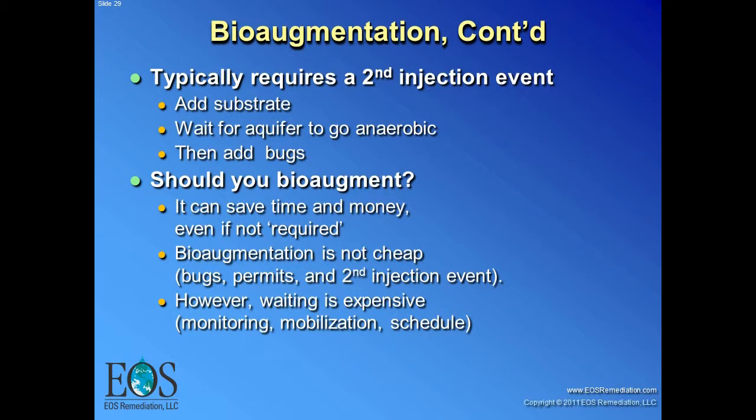The question is, should you bioaugment? Well, the bacteria are not cheap. They do cost money. The counter side of it is waiting is expensive. There's monitoring, there's permitting, there's all that other stuff. I think our bias that we've moved to recently is that we'll typically go out and sample ahead of time. If the bacteria are present at good numbers, we won't bioaugment.